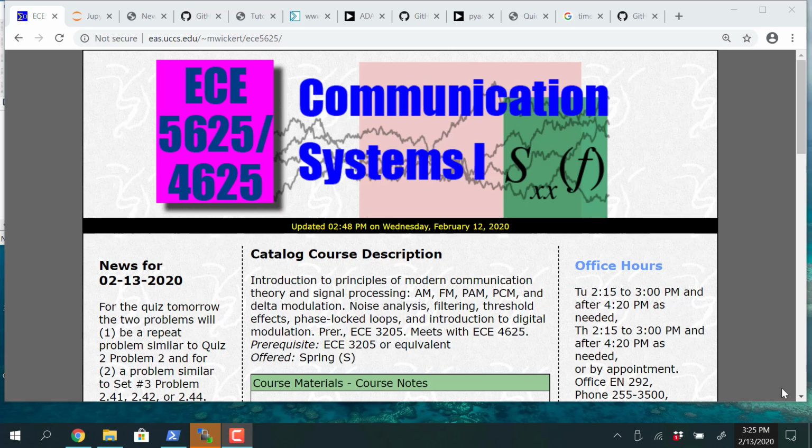To get to the autocorrelation function domain, you have to inverse Fourier transform term by term. So you get 10. I'm just reading off of Chris's paper since that's what's on the top here. You get a DC value of 10. And then you get a cosine wave at 20 hertz, which is 40 pi times tau. And then the amplitude is going to be 30 because it gets divided in half. It gets split between the positive and the negative frequency. Right?